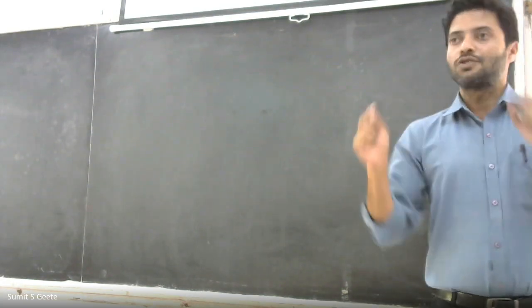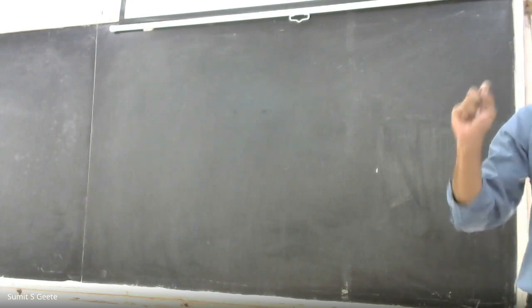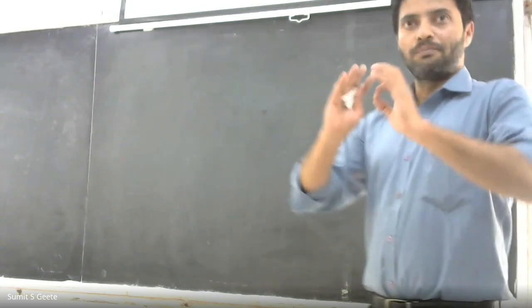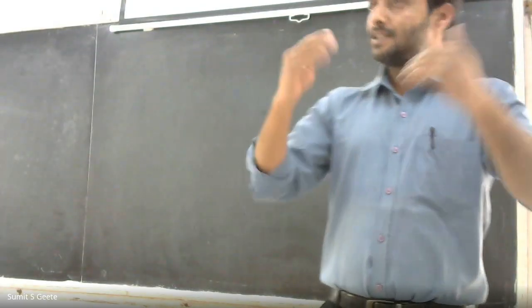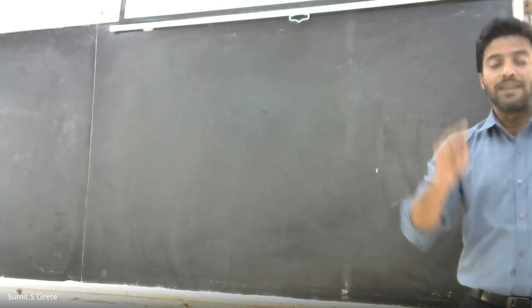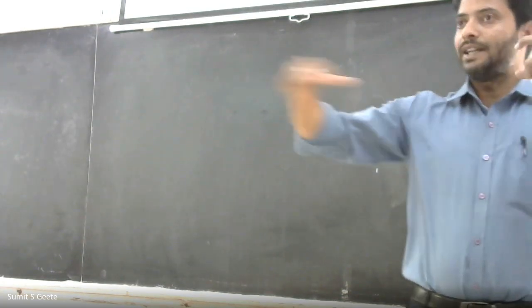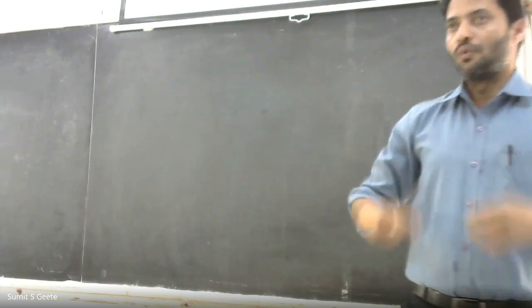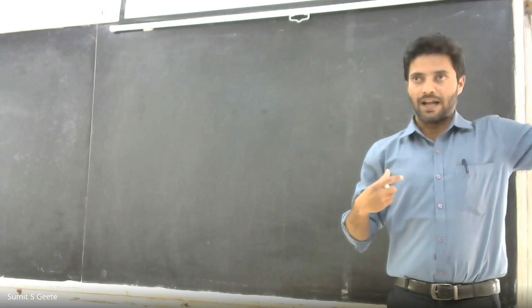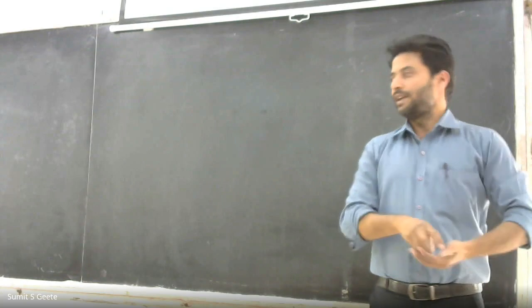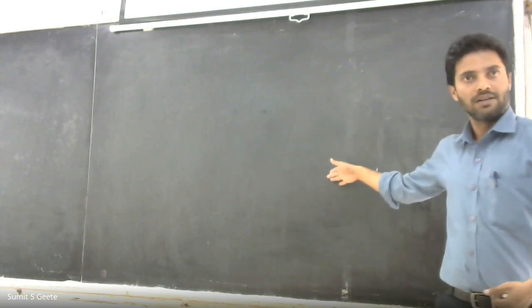But be clear, in case of frame structure, the wall acts as a non-structural member. That's it. The wall does not play any part in load transfer. It is just for partition, right? So there is no load transfer, and therefore no continuous footing is provided below the wall, right? Suppose there is a column at this end and a column at this end, then over these two columns we provide the floor beam, and over this floor beam we construct this particular wall, right?